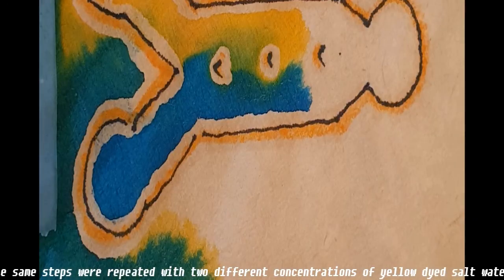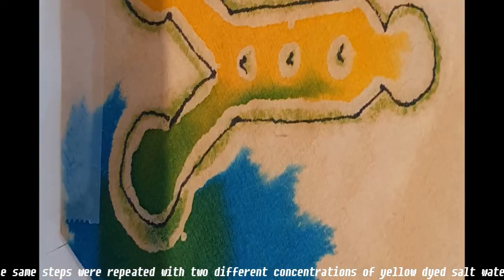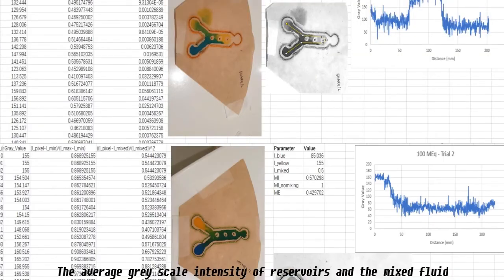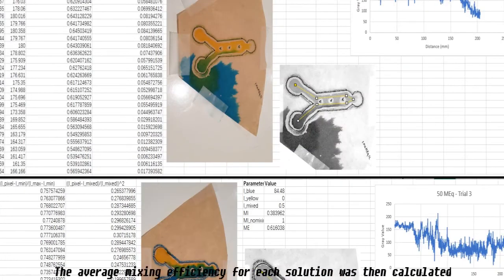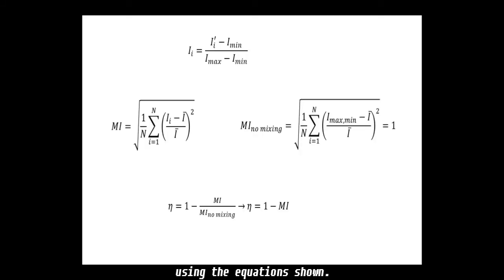The same steps were repeated with 2 different concentrations of yellow dyed salt water. 3 trials were completed for each solution. The average grayscale intensity of the reservoirs and the mixed fluid was measured using ImageJ. The average mixing efficiency for each solution was then calculated using the equation shown.